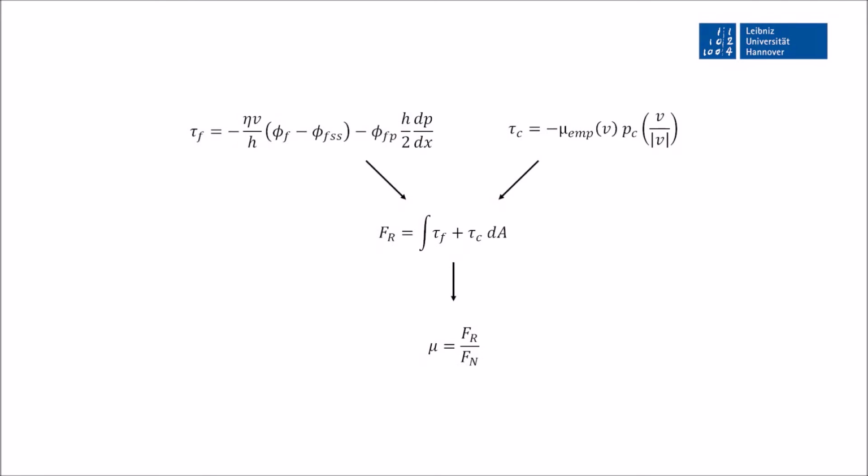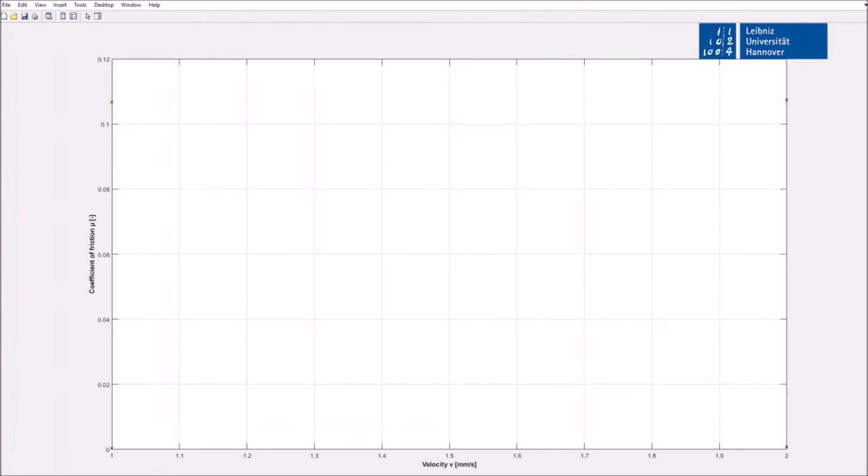In the final step, the friction coefficient in the dynamic seal contact is determined with the help of the previously calculated fluid and contact pressure, as well as the fluid film height, H. The decisive output parameter of the model is the coefficient of friction, which is determined as a function of the operating conditions and the surface texture. The resulting friction coefficients are further processed in the reduced order model of our holistic design software.